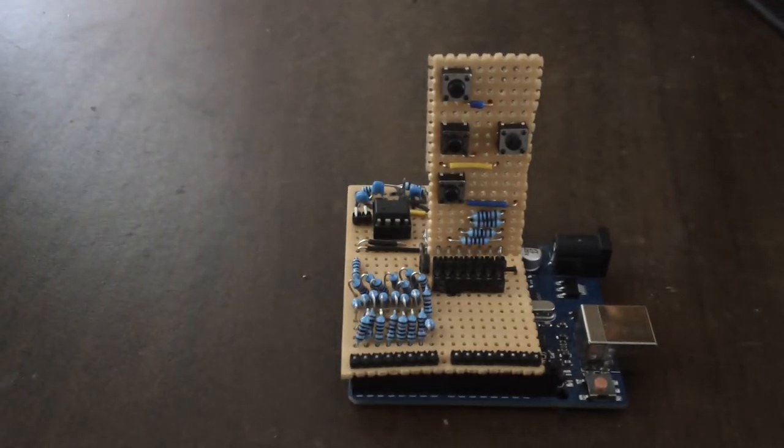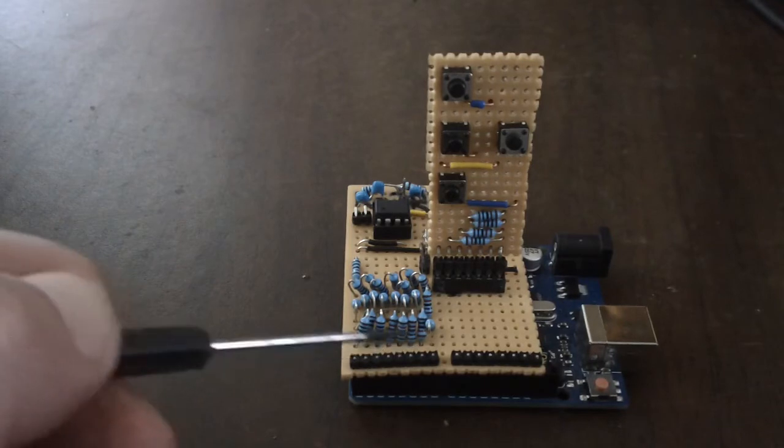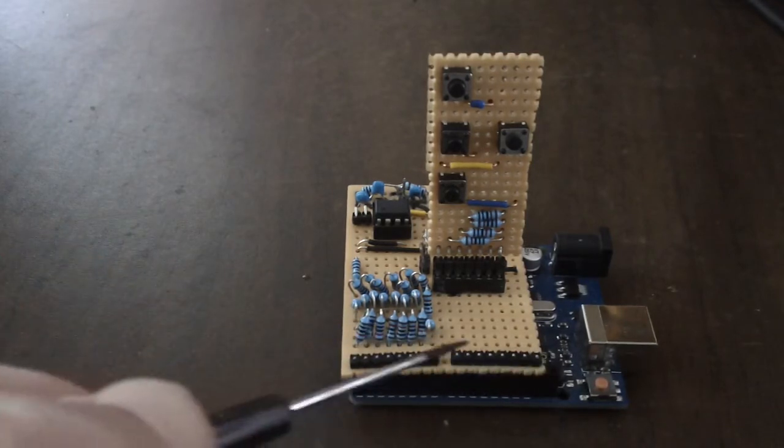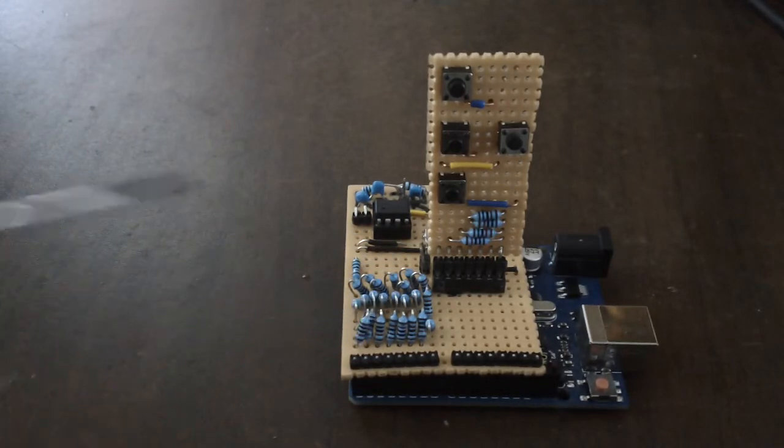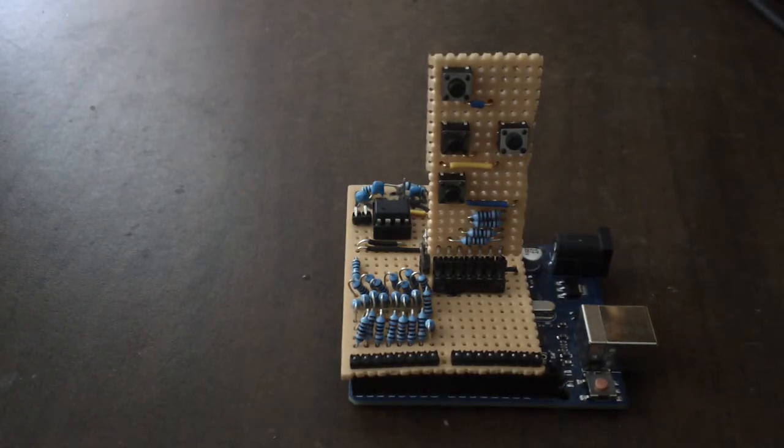Right, first things first. On this side here, that's port D, and that's port B, and this area here contains the R-2R network. If you do decide to have a go at one of these, it's quite important that the resistors are pretty closely matched. A good way of trying to establish that is if you get a bandolier of resistors, those are all 10Ks, and to make the two Rs, I've just put two resistors in series.